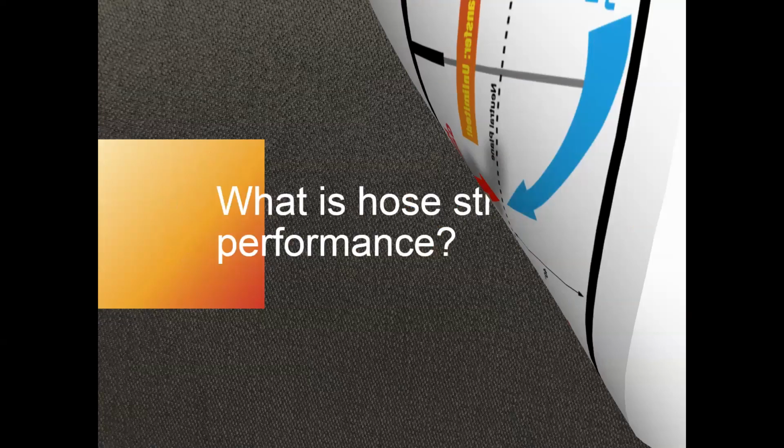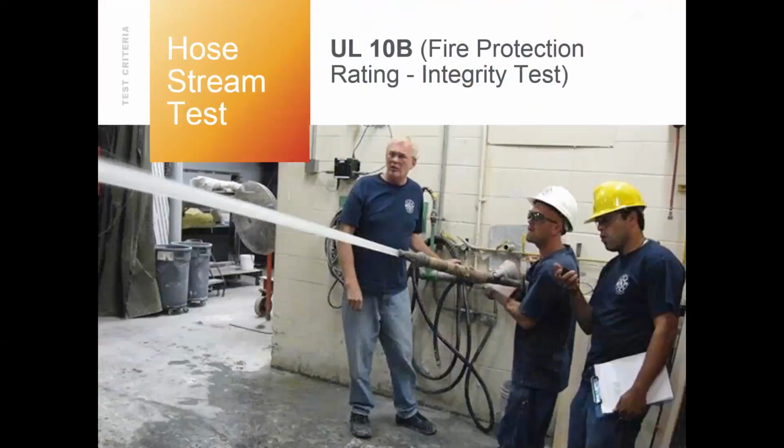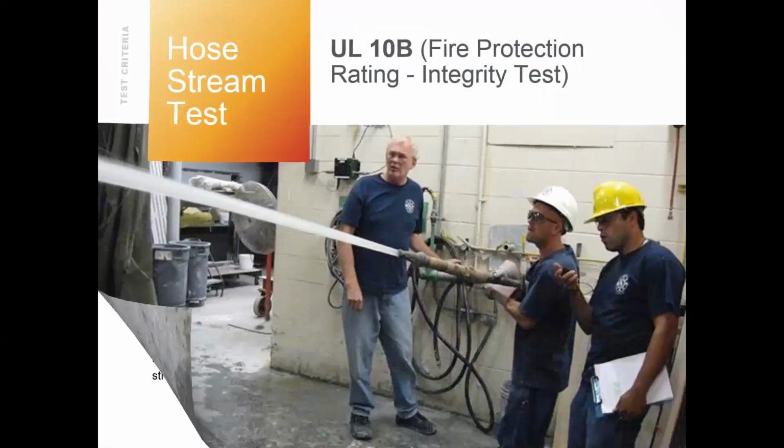So what is hose stream? We've already talked about it a few times. NFPA 252 requires all opening protectives to comply with a structural integrity test, known as the hose stream, to obtain a fire rating greater than 20 minutes. There's the code language that we can kind of see down there. And then here's a great picture of the firefighters. Why they have it, I don't know. But nonetheless, we're going to keep on going.